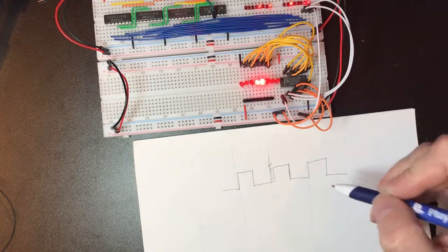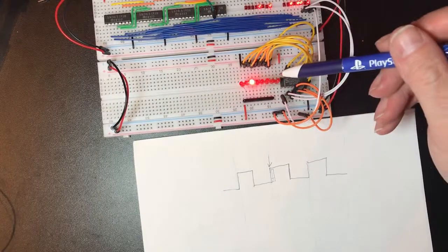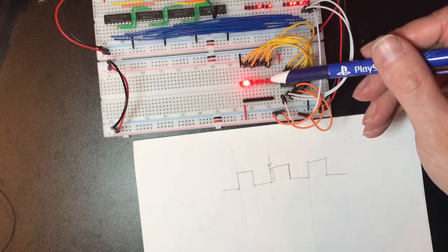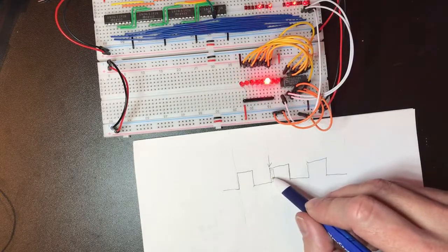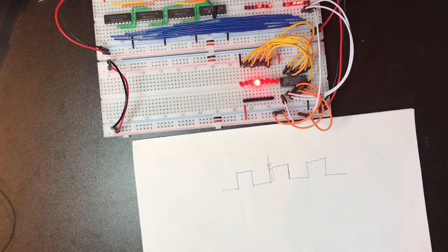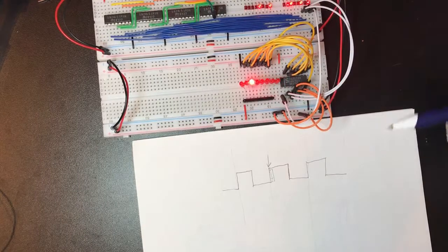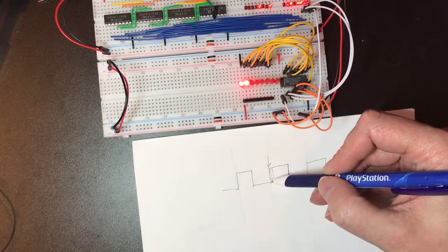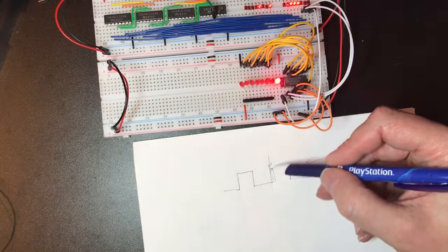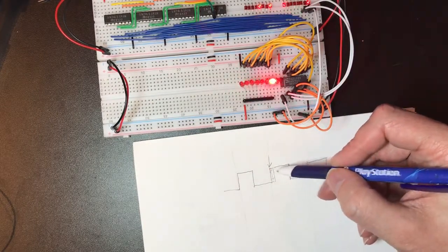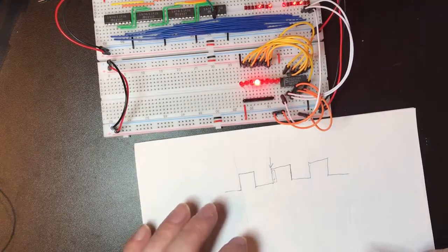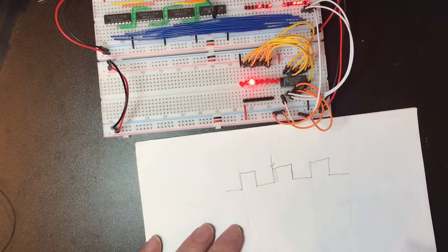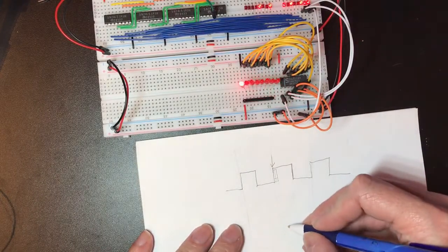So that's good, but that means that if we were to simply select the load line using this, then we would be attempting to load from the very beginning. And some of the chips we're using for registers are edge triggered, so it's just going to immediately load whatever value happened to be lying around on the bus, because this isn't quite here yet, and that's not going to work. So if we stay pretending that these lines are active high, what we want to happen is